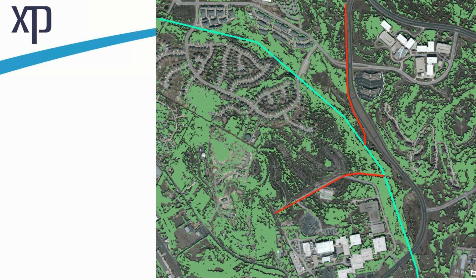Again, at the very beginning I mentioned that the hydraulic model isn't the solution, so that's not going to solve your problem. But if you're a big system that maybe is only inspecting 15% per year of your system, or if you're a small system and just don't have the funds to own and operate a CCTV, it's a great way to be able to detect areas and start specifying potential solutions based on the exact problem. And there again, you can see the line that has the most tree cover on it.